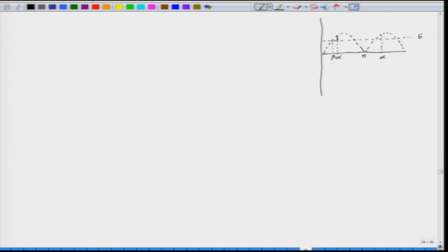So, the output voltage looks like this. This is the angle beta here. So, this goes of this sort, and this is how the output looks like. This is alpha, pi, this is beta, and then again we have pi plus alpha. Now, if it is periodic, we have the waveform which is like this. So, this is the armature voltage V A.